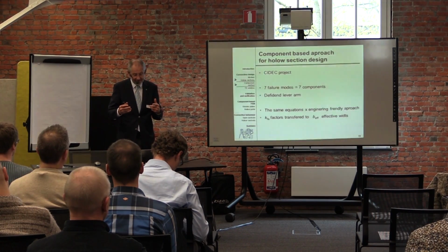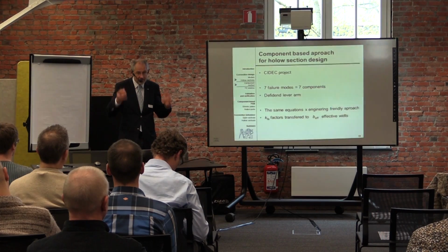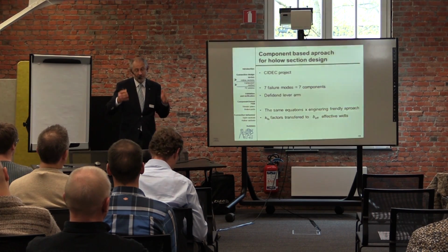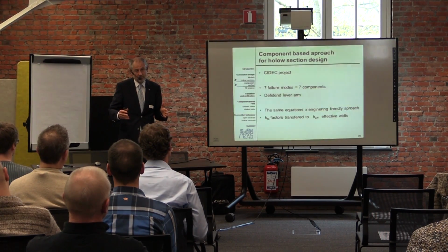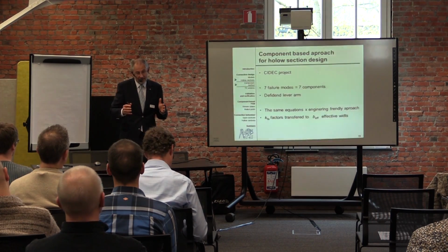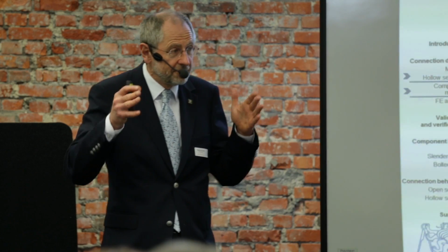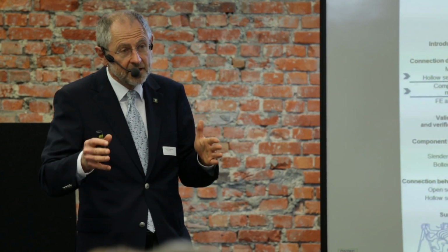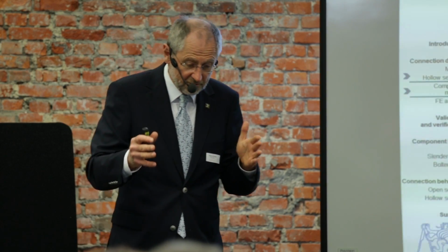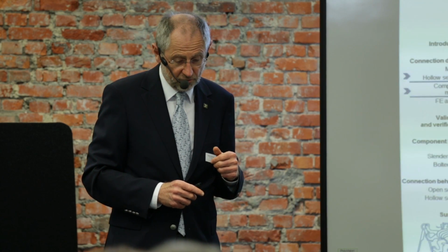I really like this philosophy, because it's engineering friendly. You understand what you are calculating, you understand what the lever arm is, you understand what the failure mode is, you understand what the effective width is. So instead of these factors, you have an effective width. You calculate what part of the joint is taken into account.